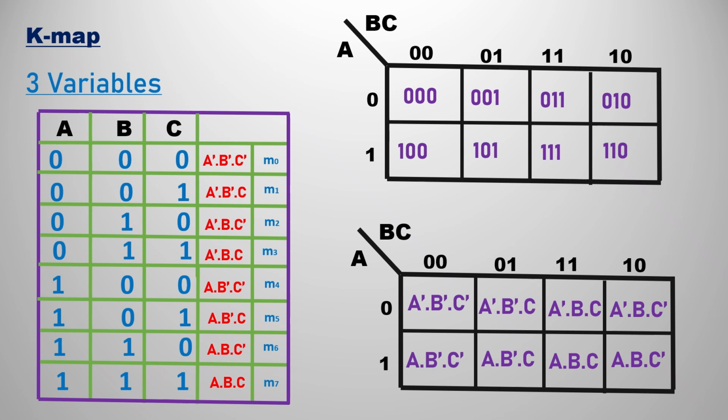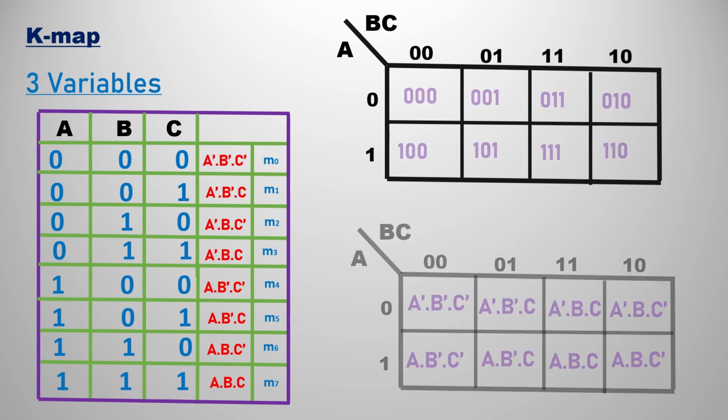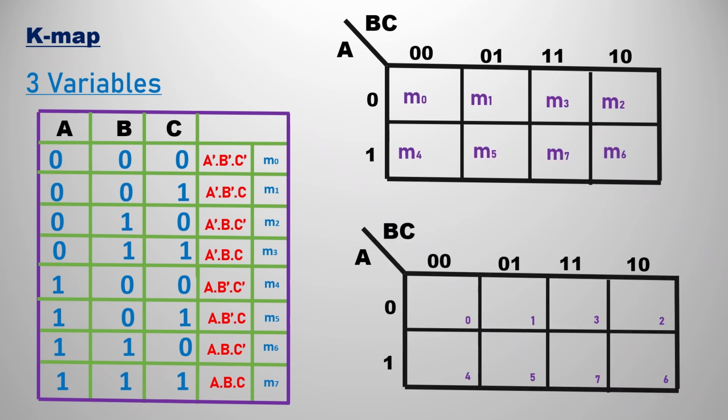So three representations are correct, because you are going to multiply rows and columns, that is A, B, C, and every variable has to be present inside the box. I think you know the normal matrix, or how you can take individual terms if you have this side term and that side term. So this is the representation of the min terms inside the boxes, going from 0 to 7, M0 to M7. See clearly, it is not in the correct order, it is a shuffled order, because we have used gray code here. Because of the usage of gray code, the digits are somewhat changed.